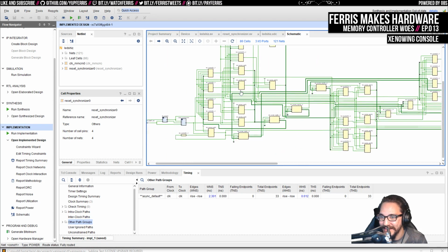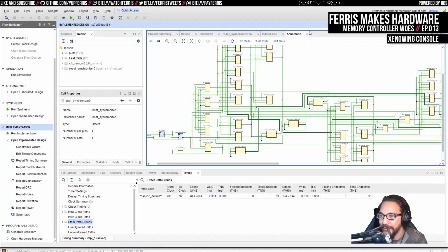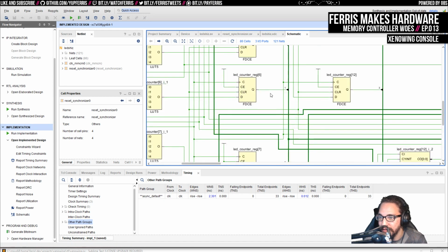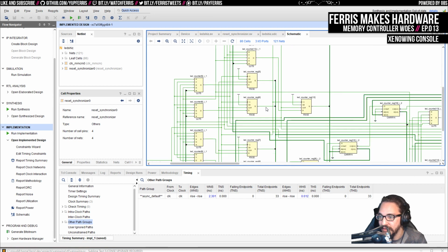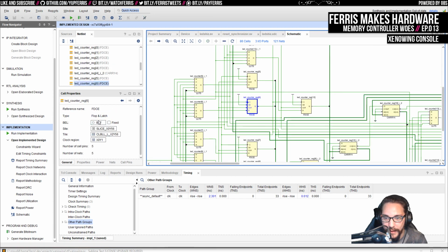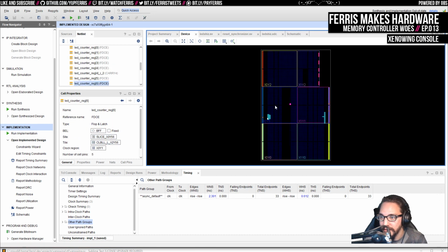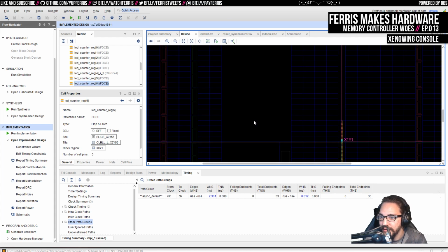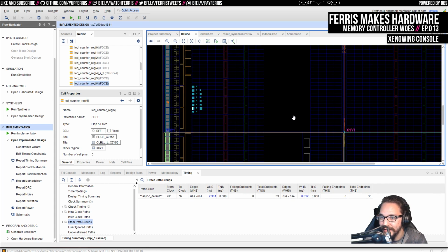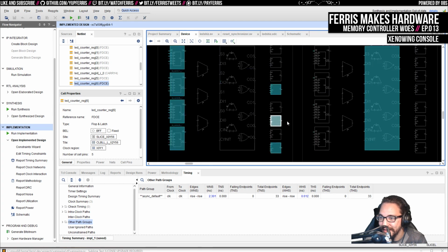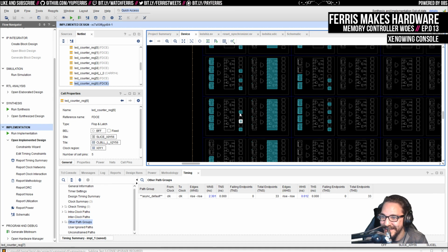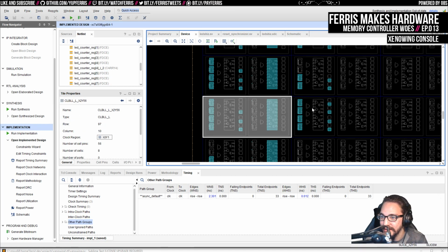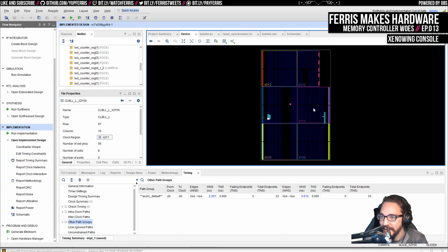It's kind of funny that it gets expanded like this in this schematic view, but it's actually also good because you can see the specific LUTs and all the different registers for the different bits. And you can click on these and get where they're mapped to in the device, which is quite cool. I guess it was down here that it ended up. It's that register. I think that's really cool that you can see all this. Gives you a very, very fine-grained view of this, actually, which is really nice. More so than I expected from this tool.